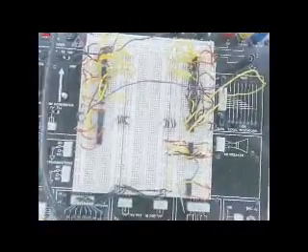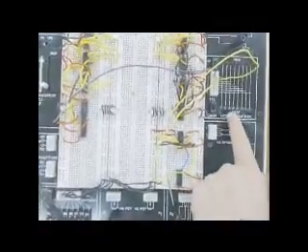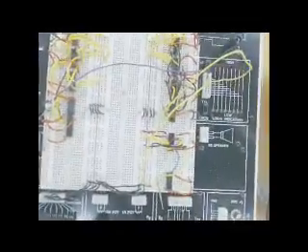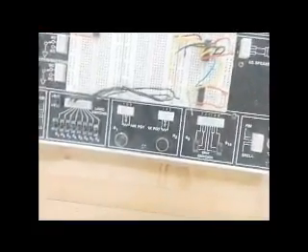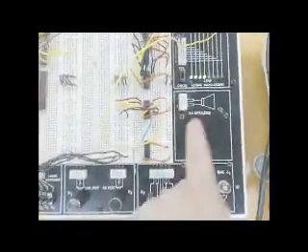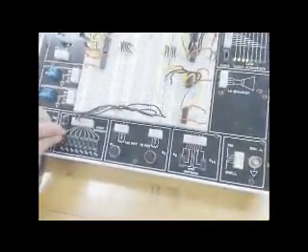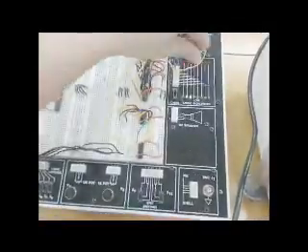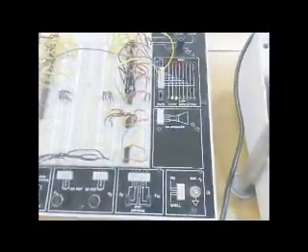So what this will do is, given any two inputs, it will give the product as outputs here. If we power this board right now, all of these inputs are 0, and so our outputs, which are these lows, are 0. For example, if we were to multiply 3 and 3, like we showed earlier, that would be 1, 1, 1, 1. Notice that our output now is 1, 0, 0, 1, which is 9 in binary. So 3 times 3 is equal to 9.